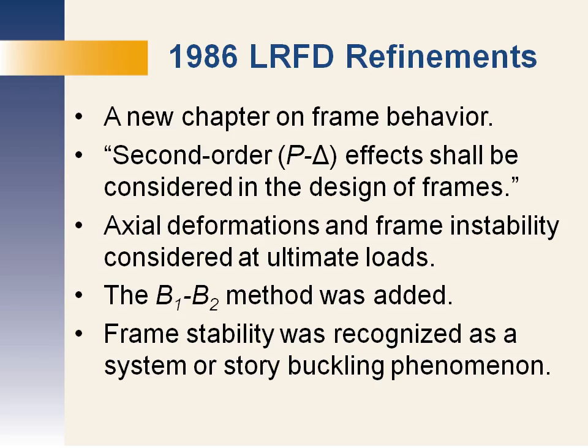There are some other significant developments at this time. Frame behavior was explicitly addressed. Frame stability was recognized as a system buckling phenomenon. And it was required that second-order P-delta effects be considered in the design of frames. Structural analysis was required to include axial deformations, and the effects of frame instability were evaluated under ultimate loads. An approximate second-order analysis procedure called the B1, B2 method also was added.